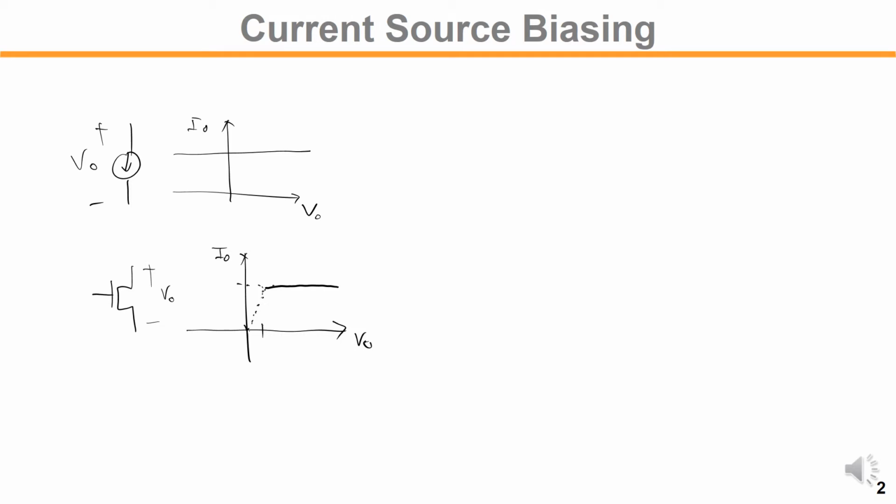So now the question is how to generate the proper VGS. Depending on the VGS, each current level will vary. For different VGS variation, our current level will change. The most simplistic approach you may think of is something like a resistor divider.